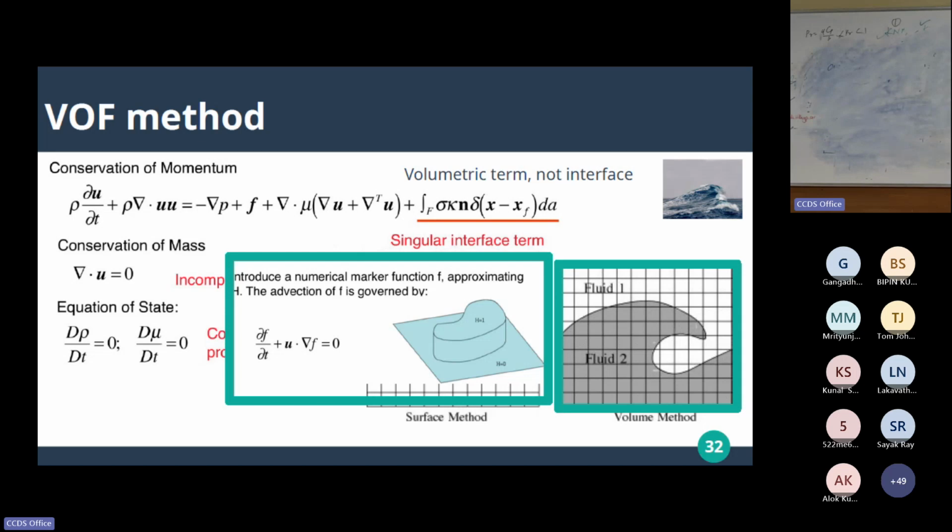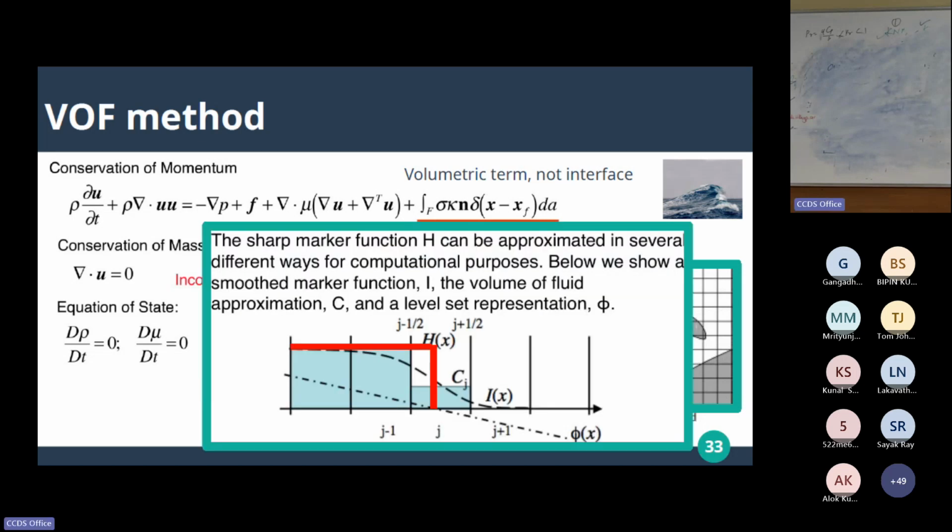If you solve this equation precisely, one should be in a position to really distinguish what is density, what is viscosity, and other things. But when you are solving that equation, we cannot directly solve it. You always have some source term, compression terms, or a variety of ways to match that kind of line. For that purpose, if you are using only the volume of fluid method, what you do is, think of this as the first mesh, second mesh, third mesh, fourth mesh, fifth mesh.